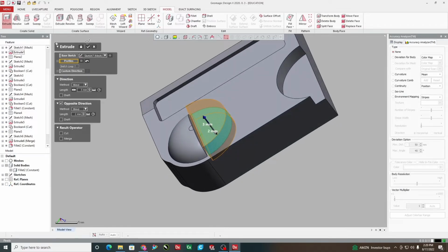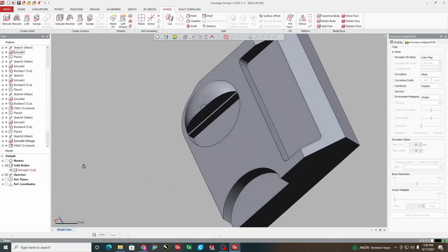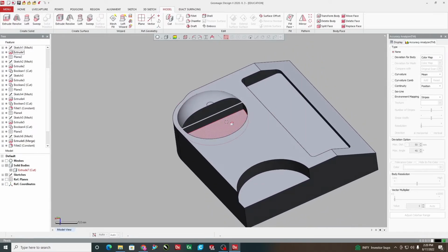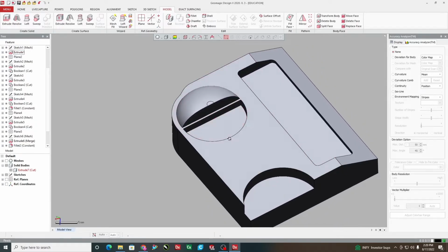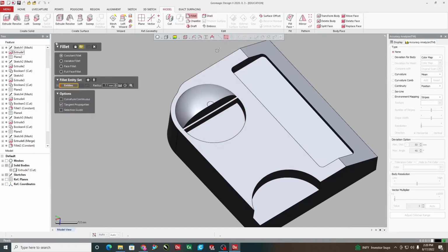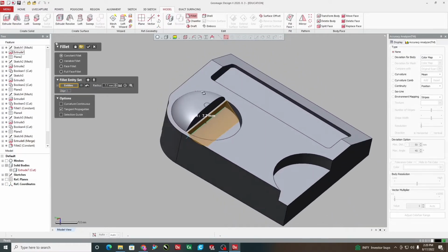Since we need to cut it down, we will again come to the extrude command and put cut extrude. We will get a cavity here using this set called cavity. We need to create the replica of the dome, an exact replica we do not know, but we will try to match it with the mesh object and try to see where the maximum green color is coming.